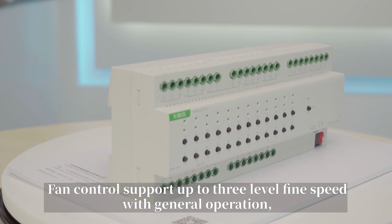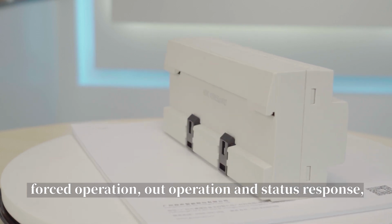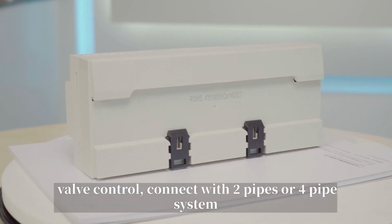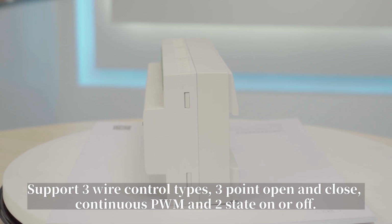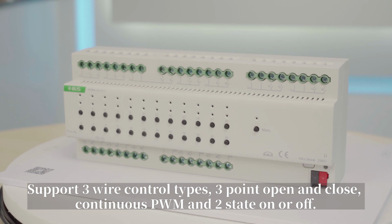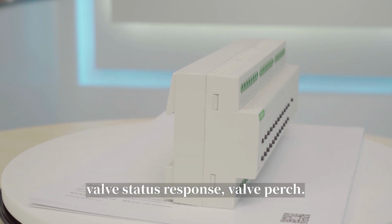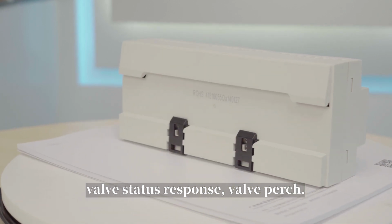Fan control supports up to 3-level fan speed with general operation, forced operation, auto operation, and status response, etc. Valve control connects with 2-pipe or 4-pipe systems, supports 3 valve control types: 3-point open and close, continuous PWM, and 2-state on or off, and supports disable, enable, heat and cool, valve status response, valve purge, etc.